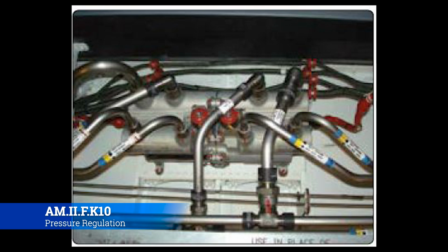In order to have that versatility to go backwards and forwards, you have to have a servo that can extend or contract, and then you have to have hydraulic fluid that can pressurize the extension or the contraction. Well, you don't want to have two separate hydraulic systems, one for the extension and one for the contraction, and even if you did, you'd have to deconflict, or they would be fighting each other.